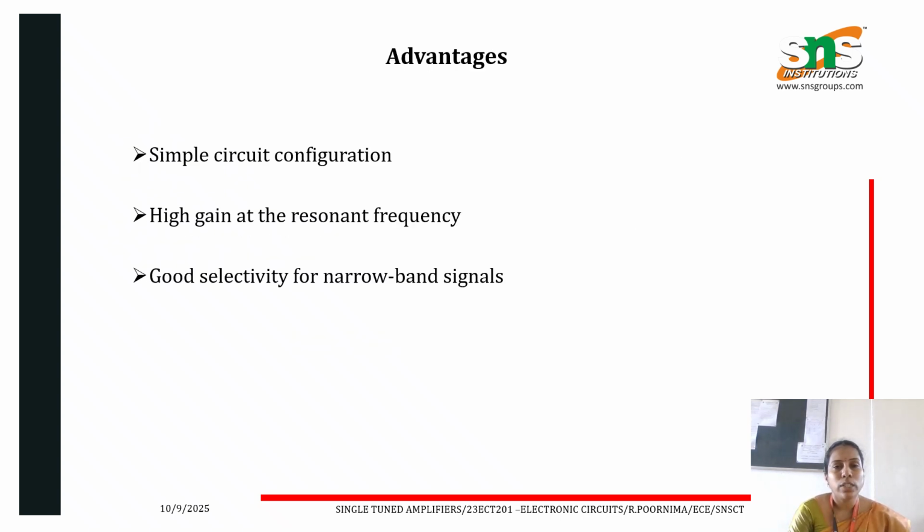And what are the advantages of single tuned amplifiers? It is a simple circuit because it consists of only one tuner section at the collector circuit. So this is a simple tuner circuit, and also high gain at resonant frequency. We have already seen the frequency response. It provides high gain at the resonant frequency, and also good selectivity.